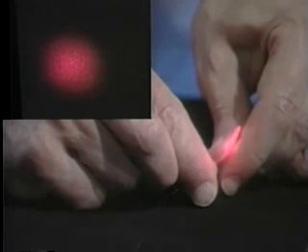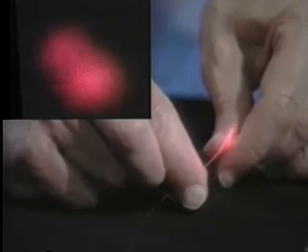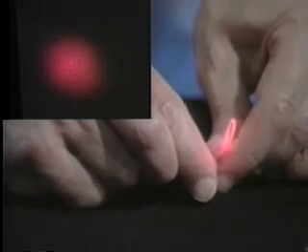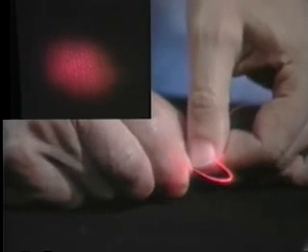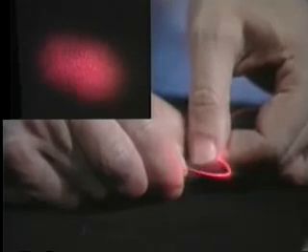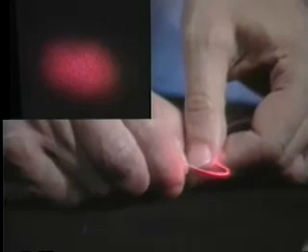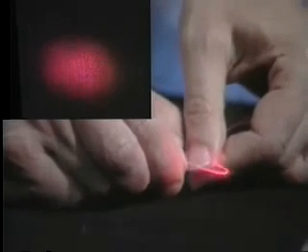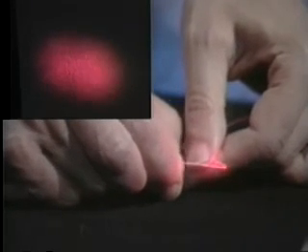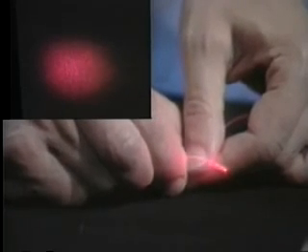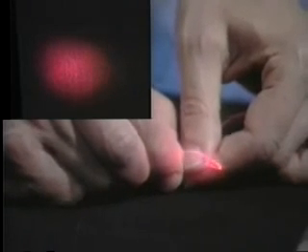So here we have single mode propagation, and here we have multi-mode or mixture of multi-modes that are propagating in the fiber. Again, you can see that there's a lot of light that gets kicked out of the fiber. You can see the bend absolutely glows. In fact, this bending effect on the transmission of light in a fiber can be used as a sensor. A sensor of pressure, sensor of stress, bends, and what have you.